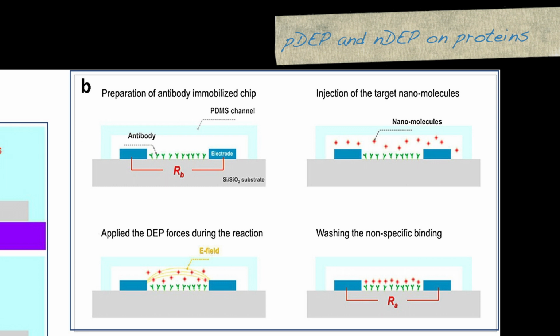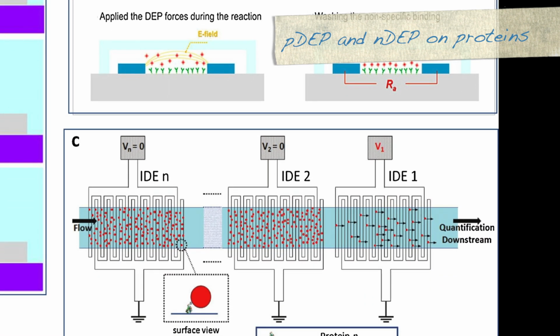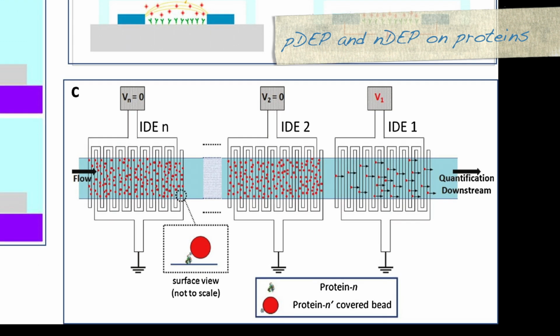Also, planar microelectrodes have been used to make dielectrophoresis gates capable of multi-target pathogen detection by performing filtration, sorting, and trapping of the bioparticles. So finally, in Figure C, the schematic shows a multiplex detection biosensing using an array of protein-modified elements and arrays of interdigitated microelectrodes.